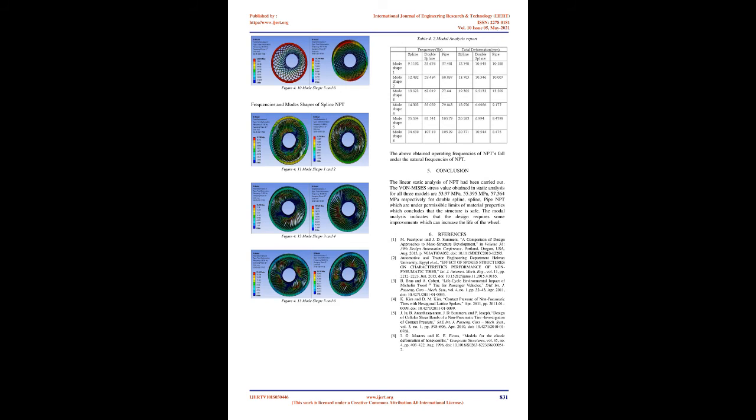The main reason for the selection is that they have a wide range of mechanical properties such as high rigidity and strength, high flexibility, hyperelastic resistance, high temperature resistance and other factors. Table 3.2 gives the materials assigned to each part and its properties. The internal surface of the wheel is fully restricted in all directions, as the hub of the wheel is fixed and acting as a permanent support for the wheel.